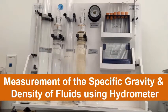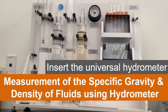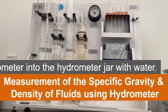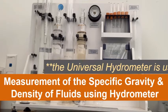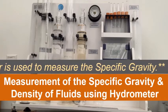And then we will insert the universal hydrometer into the jar. Let it settle and stabilize before we take the reading at the surface of the fluid.